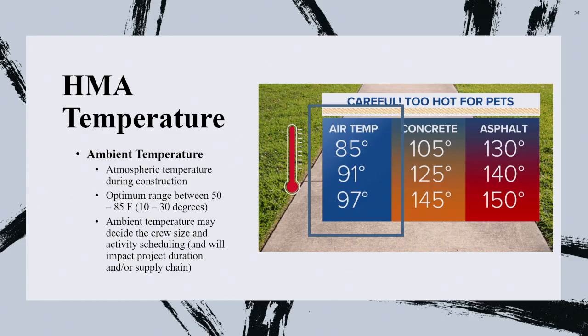So basically it's giving you guidance on what kind of temperature you do the mix at. I think ours is different. We produce at 143. So by the time we do our haulage distance to the site, it will lay at 130. Yeah, 143 to 130, it's very close. It's because of our temperate region. I got the point that you're trying to raise.